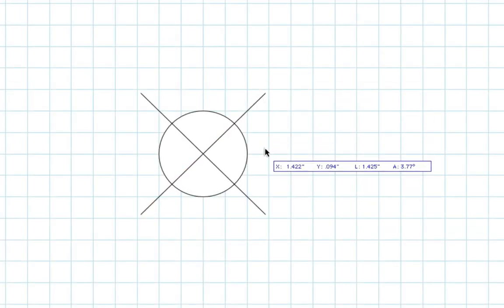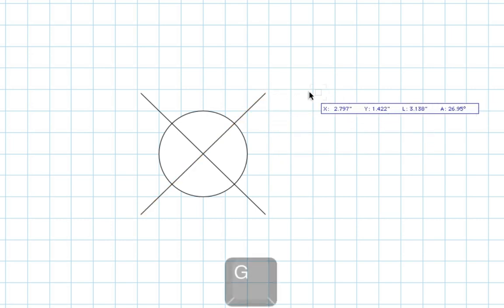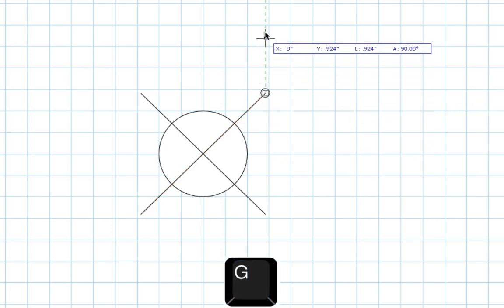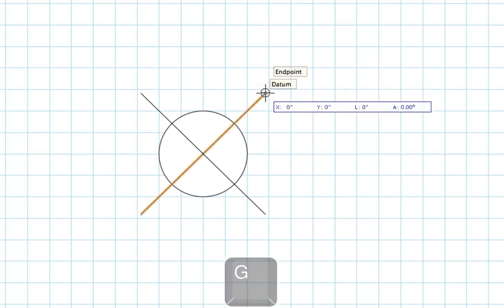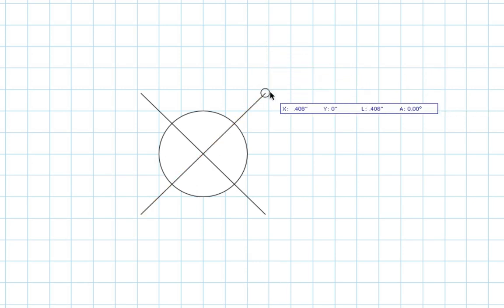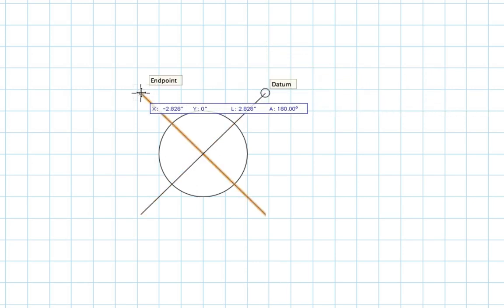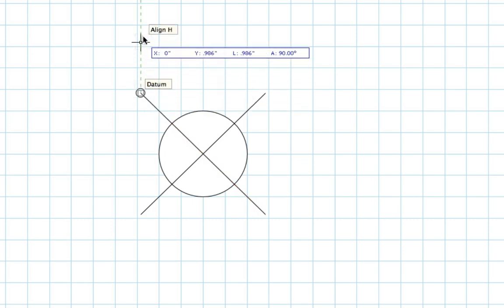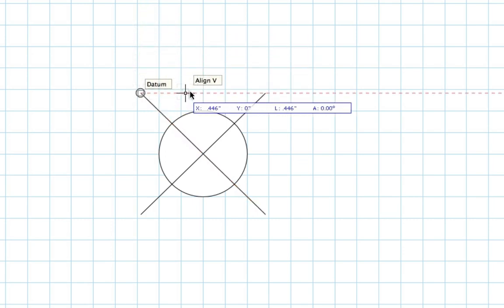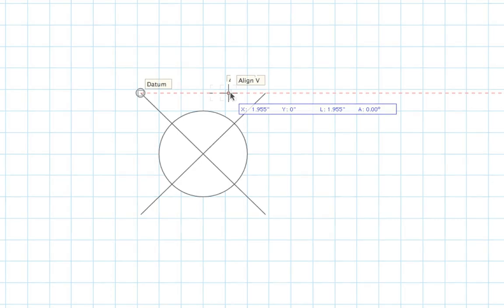Now, when you create a floating datum via the shortcut G key on your keyboard, the floating data bar will appear automatically, making it clear that any moves or data entry will be performed relative to this newly created datum rather than to the actual X and Y coordinates of the location at which you created it.